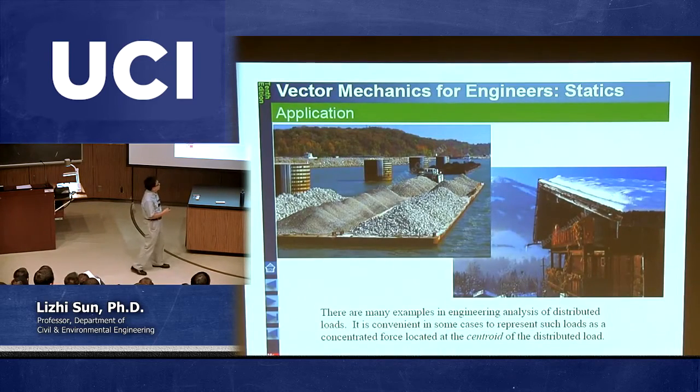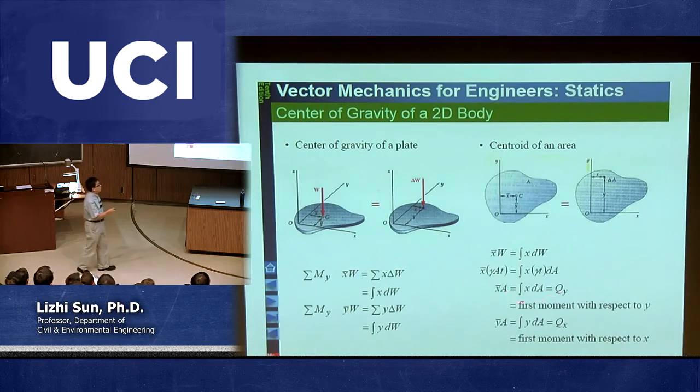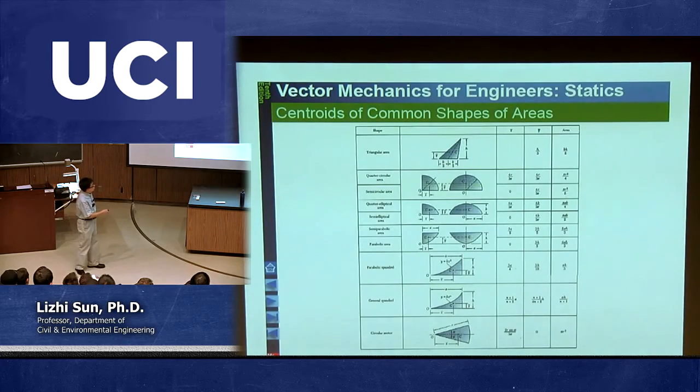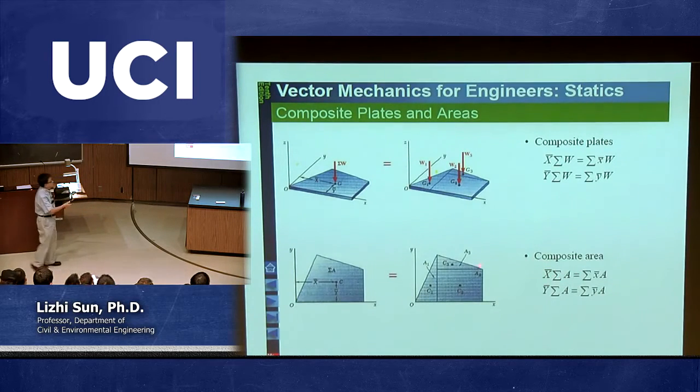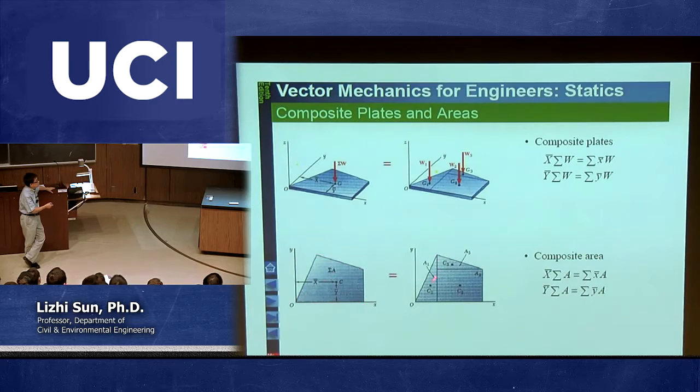And the centroid calculation is what we call x bar, y bar. Okay, following the final equation having x bar equal to this one divided by A, y bar equal to this one divided by A. But in general, we're not going to ask you to do integration by yourself. So what we're asking you is basically using the composite rule to calculate the centroid x bar, y bar in capital by splitting a more complex area into a few simple areas. And that procedure is called superposition.